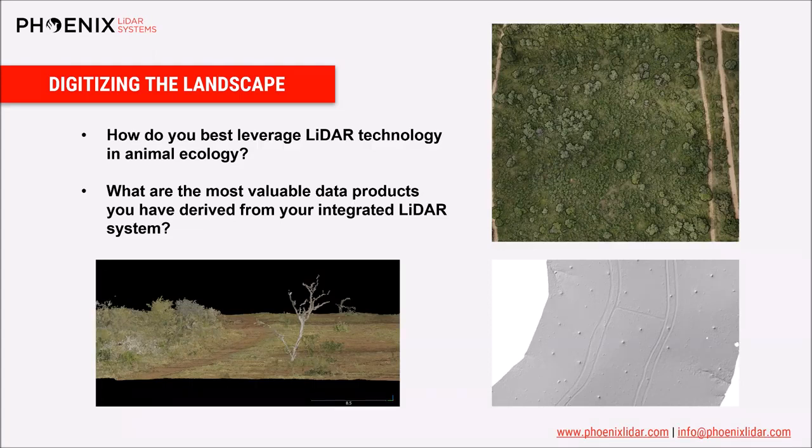We don't have a set product we'd use, but pretty much we use point clouds, digital terrain models, so that's without the vegetation, the surface of the earth, digital surface models, which is the highest value for given pixels anywhere, and canopy height models, which tells us the height of the vegetation. You pretty much use those or some sort of fancy product that's derived from one of those further downstream. That's our typical go-to with LiDAR.